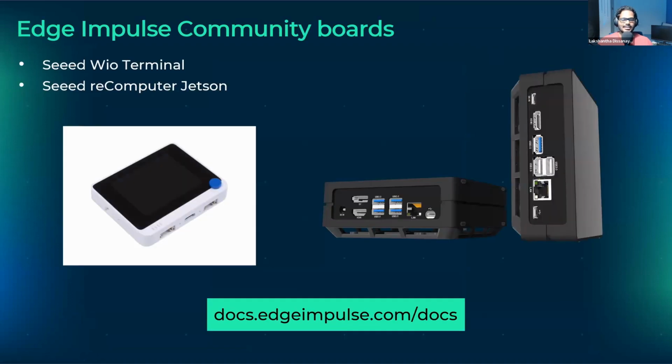Yeah. And also quickly, I want to mention the Edge Impulse community supported boards. There are some community supported boards available on Edge Impulse, and 2 of them are by Seeed. This is the Seeed Wio Terminal, the one I mentioned before as well. This is an Arduino based microcontroller with an LCD and a couple of sensors built in, like a light sensor, accelerometer, microphone, and a buzzer. So when you connect the Wio Terminal to Edge Impulse Studio, you can, for example, do a speech recognition project because it has a microphone. And it has a light sensor, so based on the light, you can do some detection. And there's an accelerometer, so based on hand motion recognition, you can do some AI training. So this is the board.